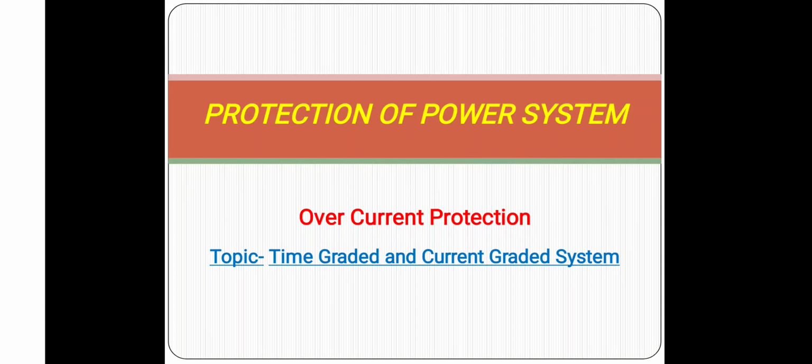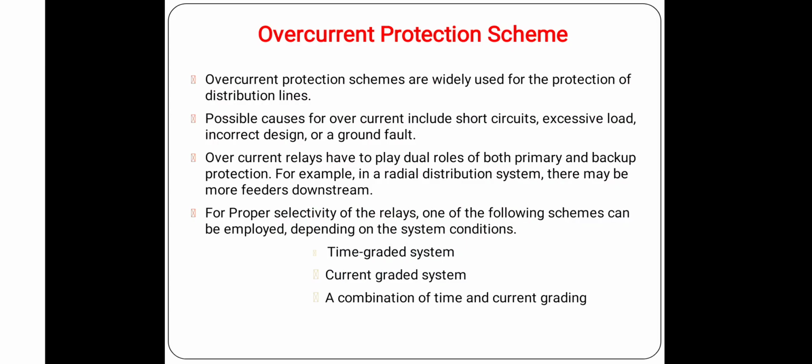In today's continuous lecture of overcurrent protection, we will study a very small topic, that is time graded and current graded system. But this is a very important topic regarding the overcurrent relays. So first we need to know what the overcurrent protection scheme is for basically feeders, ring main systems or parallel feeders, where we can use the concept of time grading and current grading.